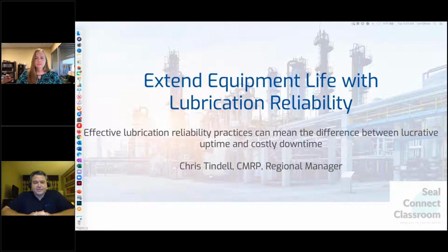So cans and funnels. But I think probably the strangest application, we were looking at a pump in a mining application, and it was a temperature issue. And we discovered that the maintenance technicians had decided to move from an ISO 68 oil to a 220. And what that basically means is that 68 is like comparing water to syrup, and so that was causing the high temperature.